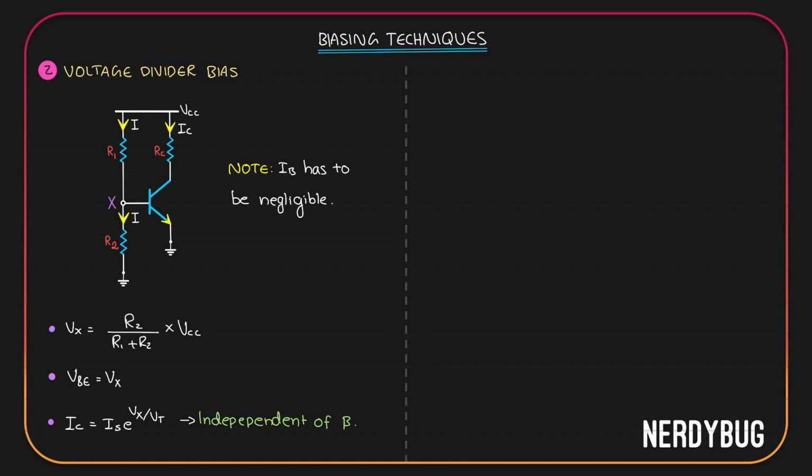Now, how will the DC load line look like? Let us take the collector emitter loop. VCC is basically a cell that is connected to the ground like this. So we have this loop. If we apply KVL, we get VCC minus the potential drop across RC, which is ICRC, is going to be the rest of the potential, which is the potential between the collector and emitter, VCE.